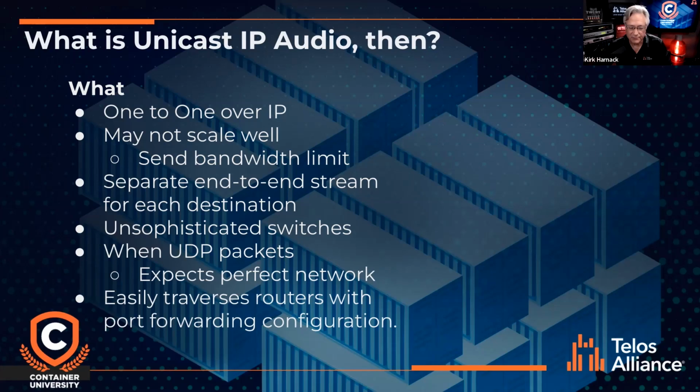UDP easily transfers through routers with port configuration, and I should say UDP in Unicast. So Unicast can easily traverse a router just by doing port forwarding configuration. So it is okay for remote operations through things that can't accept multicast. They can certainly do Unicast.